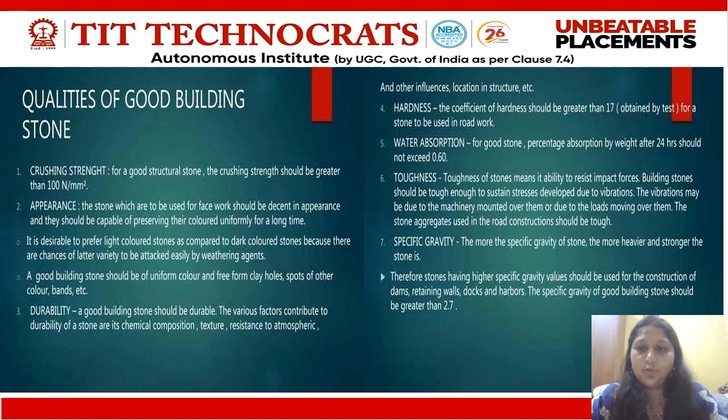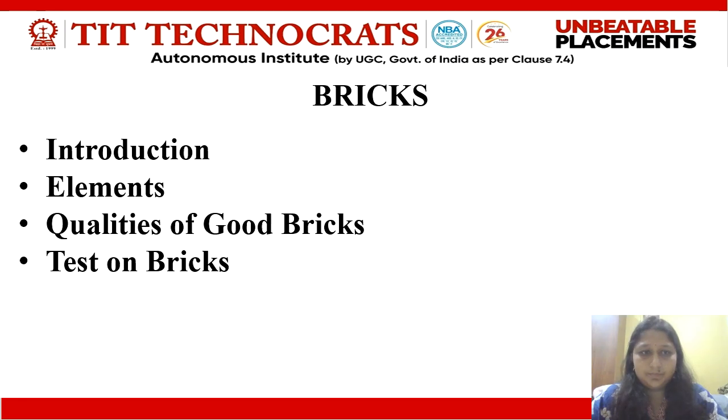Its coefficient of hardness should be greater than 17. For a good stone, the percentage of water absorption should also be minimum. The stone should be tough enough to bear the impact or sudden load coming onto it. The more the specific gravity of the stone, the heavier and stronger the stone is.